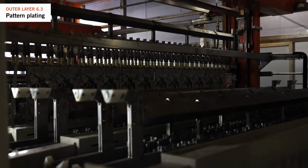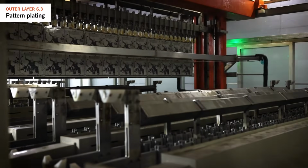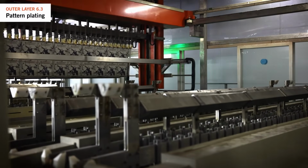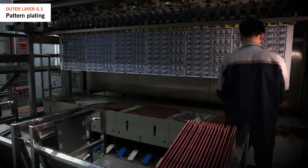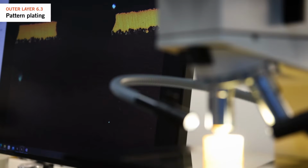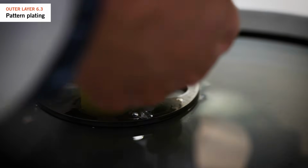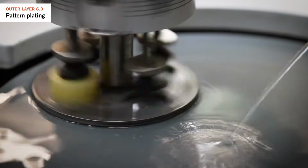Ensuring a uniform deposit can be a challenge due to design, with isolated external areas potentially plating higher. The right setup on plating flight bars is important, as are thickness deposit checks to ensure good levels of plating uniformity are achieved across all panels. Final plating thickness is verified through microsections and non-destructive methods.